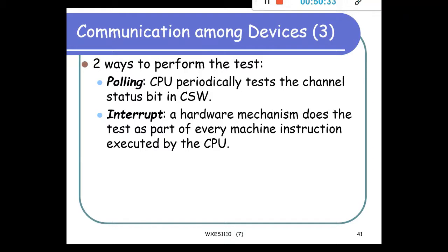The interrupt handler determines the best action to take based on the current situation. Since more than one unit can cause an input output interrupt, the interrupt handler must determine which unit sent the signal, analyze the status, restart with the next operation when appropriate, and finally return control to the interrupted process. So you have polling and you have an interrupt.